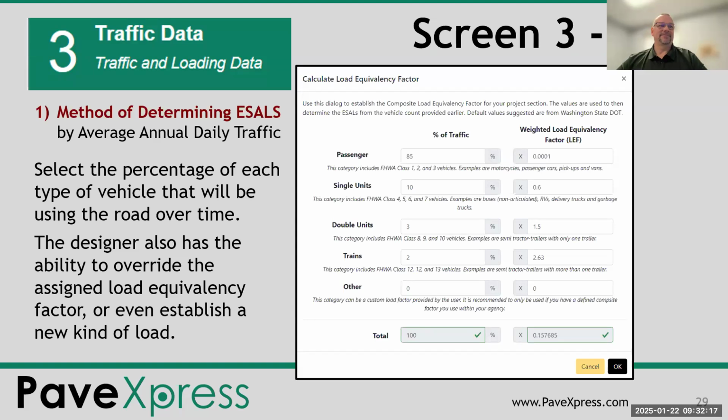And then one last question here. Is there a good rule of thumb for a top end for a growth rate, where you'd say this would be ridiculous because cars aren't going to be able to get through? Some of that gets into how many lanes you have and things like that. You don't usually see growth rates over 5%. You can look at historical data. I think when MDOT does their designs, they usually have historical data, and then they project a similar growth rate. I've never seen one over 2% that they use.